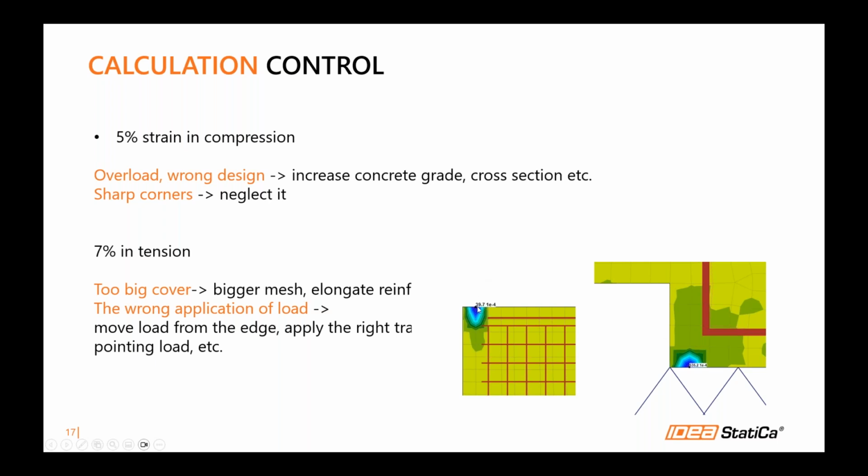Or for example, if you input a point load at the edge, or when you input a force that causes tension in the concrete and it's not connected with the reinforcement, it can cause it to fail. So it's not necessarily a wrong design, but a wrong understanding of the application and of the inputting of the loads.